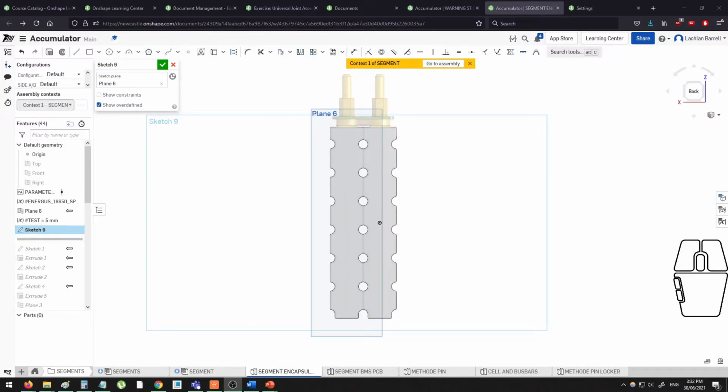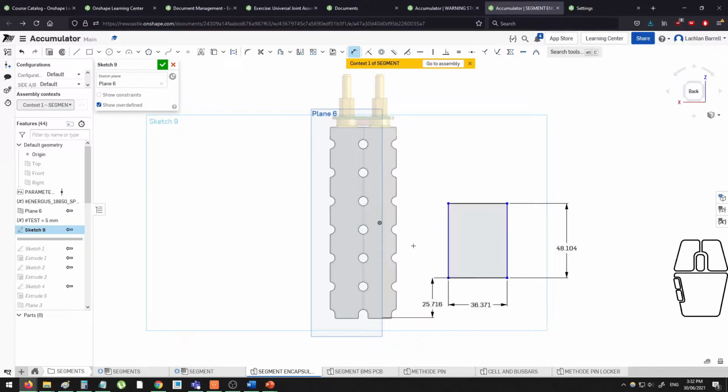Alright, so now I'll start talking about using constraints in Onshape sketches. So if your sketch ever has blue color in it, that means that something is not fully defined or constrained. Usually that means that it's missing a dimension or a constraint like vertical, horizontal, coincident, or equal, or something like that. Generally speaking, you should never leave a drawing with undefined geometry in it. It means that it could be fairly unstable. However, sometimes it can be somewhat unimportant.